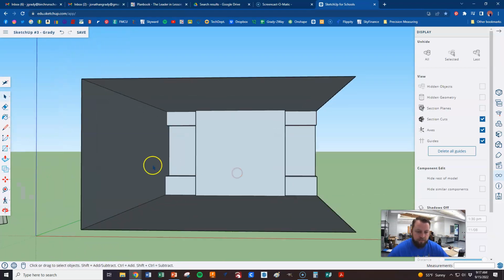What I want you guys to kind of play around with right now is if you go over here and click on this bottom, this gives you all the zooming tools, right? And if you click on this magnifying glass, in the bottom right down here, I haven't clicked anything, I'm just hovering, it says the field of view is 35 degrees. So I still haven't clicked anything. Let's change that to 50.